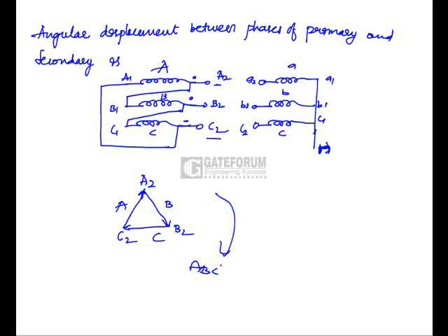Now this is the phase sequence, A, B, C in primary. Now we have to draw the same way on the secondary side also. Here at the bottom I have C phase, so I am taking C here. Now this is the C2 winding. Let us take this one as neutral N. On the secondary side we represent with small letters, so I am taking small n.